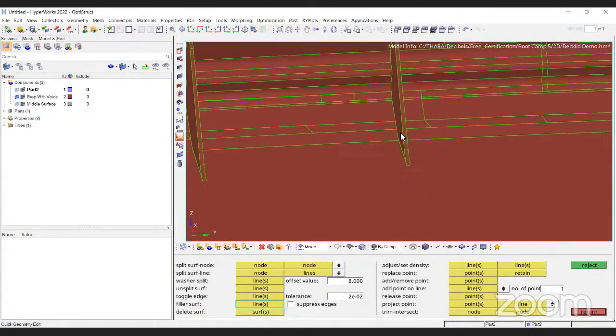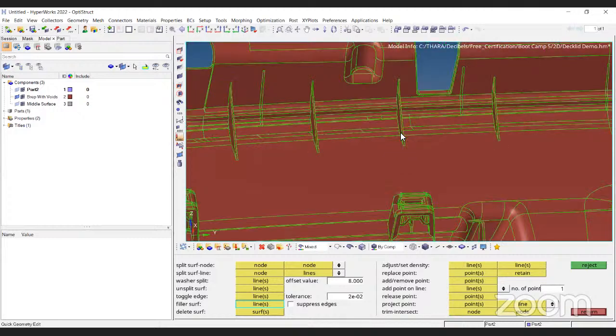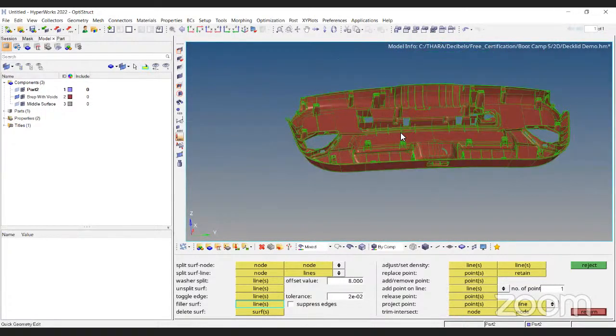So when the component is plastic, when we are going to create only the 2D mesh, and when the thickness is defined within the range, then we need to extract the mid surface. On that mid surface, we are going to create the elements. So this is the basic idea behind why we need to extract the mid surface to create the 2D elements.